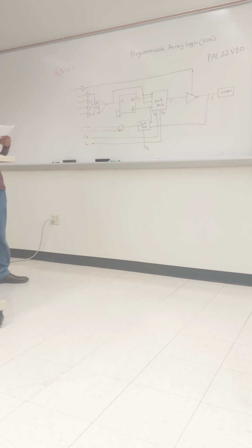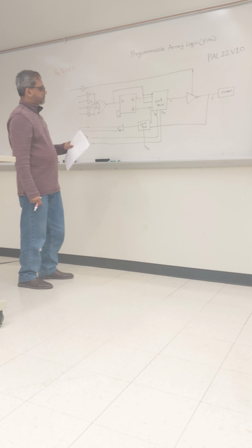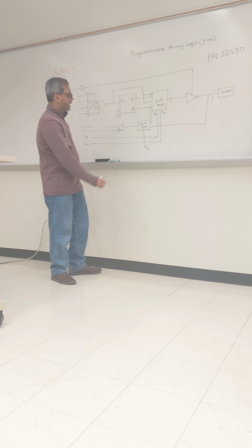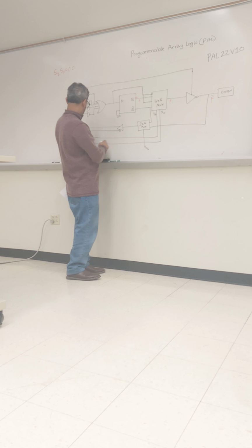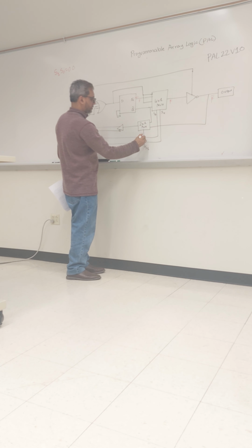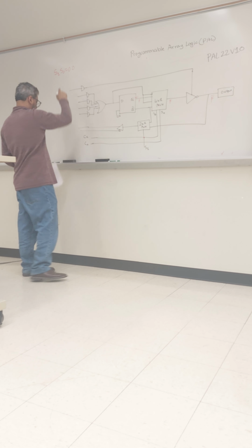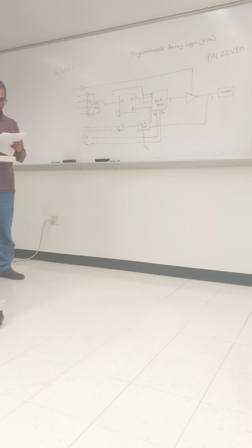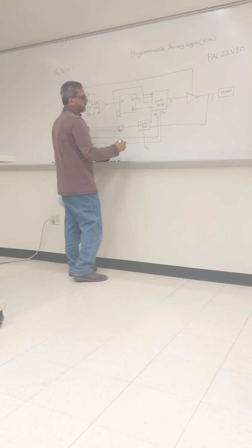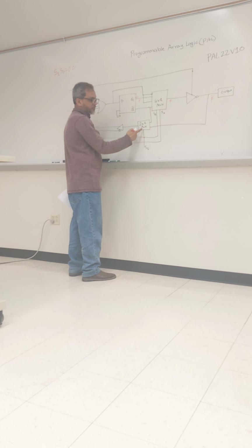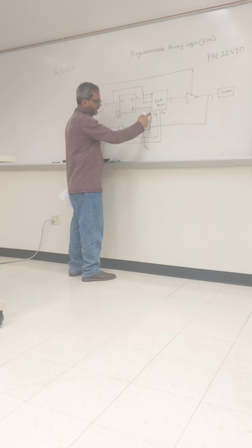Okay. What about at this time? What will the 2 to 1 mux do? As you can see, this is also S1, for example, the C1. So S1 is equal to 0. As S1 equals 0, the Q bar output of the flip-flop will be fed back to the input side. As this is the true input, when it is 0, it will take this one.